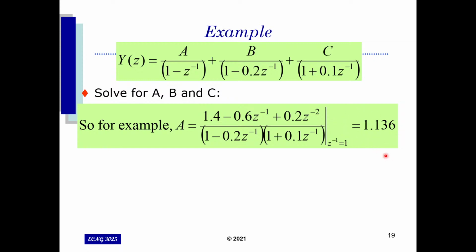So this method, which we use for solving partial fractions, is effective when all these terms on the denominator are not repeated. These need to be independent and unique terms on the denominator. If for some reason you do end up with a repeated term, like if one of them was 1 minus z to the negative 1, and this one here was also 1 minus z to the negative 1, and so forth, the partial fractions themselves are going to take on a completely different form, and that means you're going to use the manual evaluation method to solve for your coefficients.